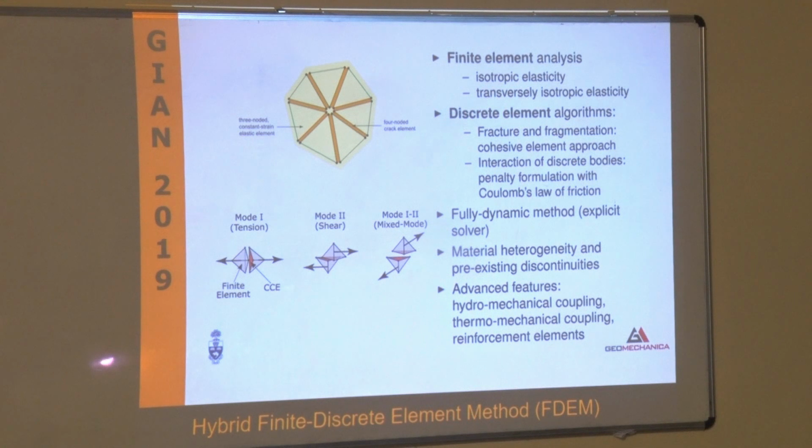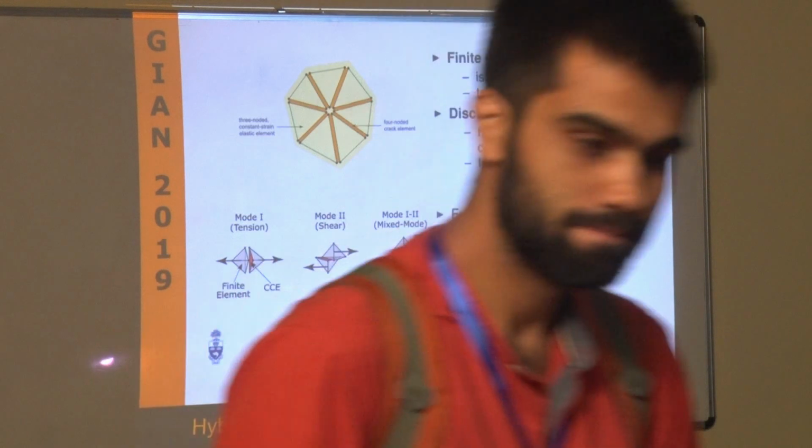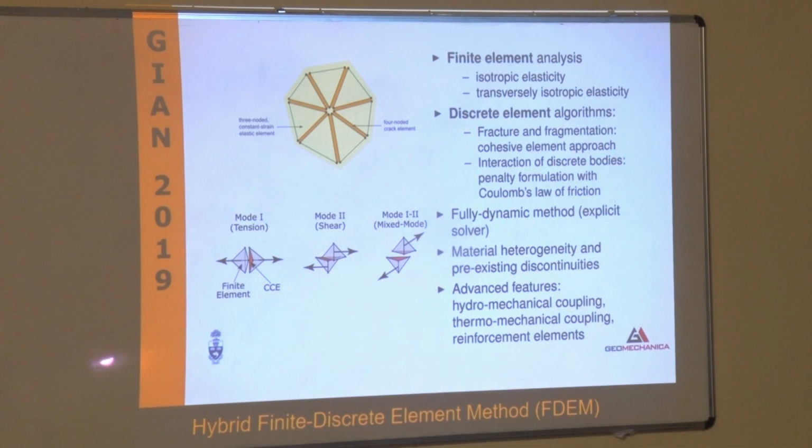Plus, you can add a lot of additional physics, such as the thermal stress. So it means that your system will respond to change in temperature by dilating or contracting. You can add fluid. That means that it could be a pore pressure, meaning that you have a pressure within your system. And that is really typical of solid mechanics, pretty much. But you can also have fluid within the fractures. And that, going back to yesterday, can be simply captured through a cubic law.